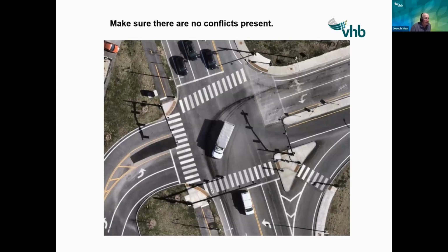And what I mean by that is when the walk signal is on, the button will vibrate. So it'll give an indication that it's a go indication to go across the street. When I check this particular intersection, I press the button to walk across, this button here, and it wasn't vibrating. This button was vibrating, letting a sight impaired person know that this crossing was all right. And this was green at 45 miles an hour. So it was a conflict.